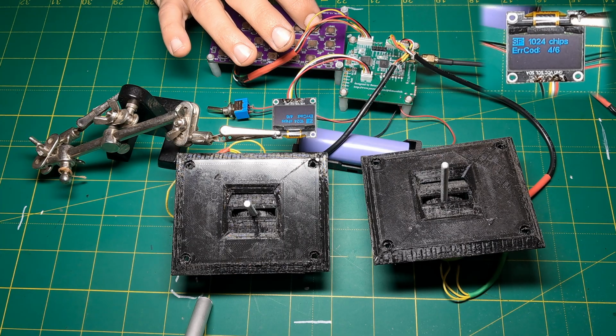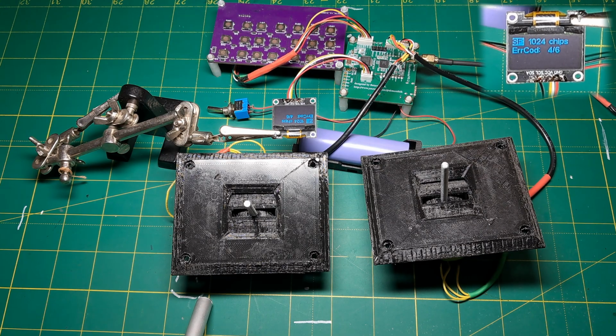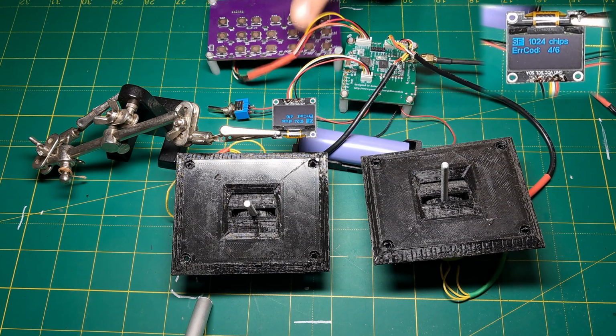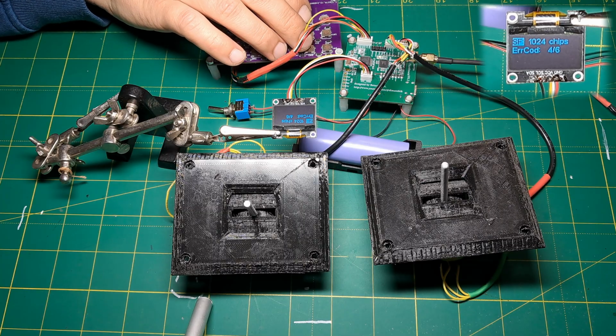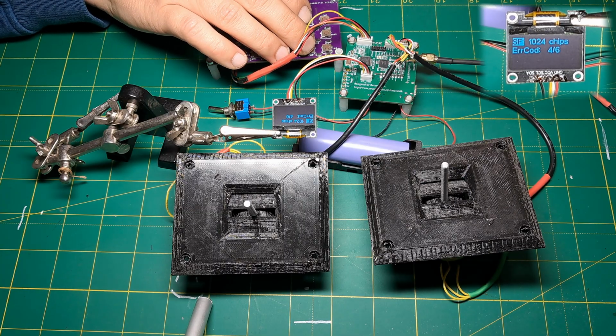I'd like to point out that when you first launch the sticks, their zero position is either read from memory if you have previously calibrated them, or the current stick position when you turn on the device is used as 0. If you accidentally set the sticks beyond 0 during startup, the default values will be applied, or the ones you saved during calibration. Let's perform a calibration.